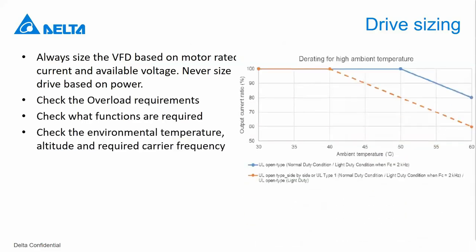You might have to derate. So derating means that you select a drive of a higher rating than that of the motor. And some typical conditions when you might have to do this is when there is a very high overload requirement, or when there is a high temperature.